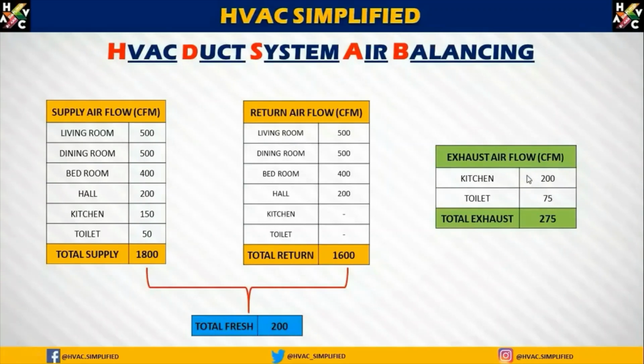Now as you can see, the kitchen and the toilets will be having exhaust. So the exhaust requirement of the kitchen is 200 CFM and the toilet is 75 CFM. Therefore the total exhaust requirement of this particular zone is 275 CFM. Now as you can see, the exhaust CFM is more than the fresh air which is required. So therefore the total amount of fresh air required in this particular system will be 275 CFM.